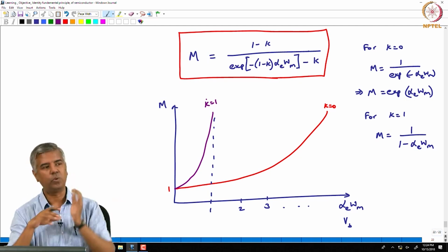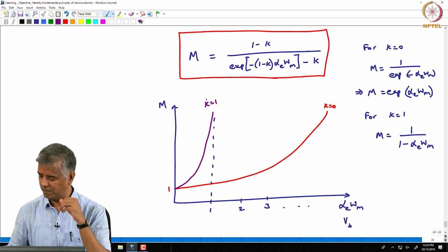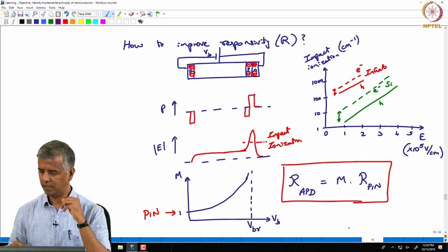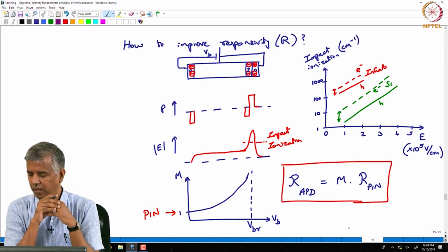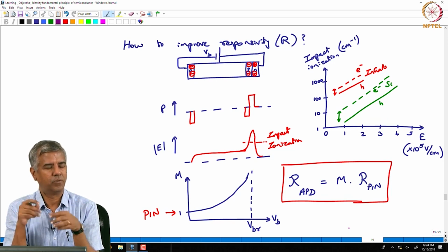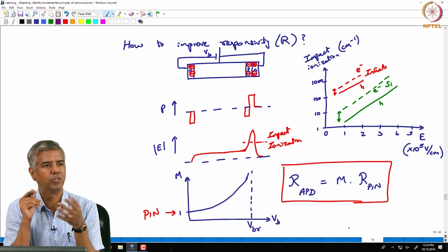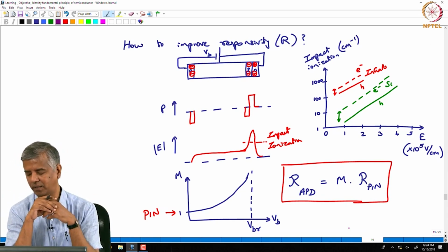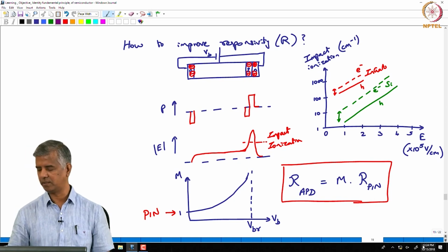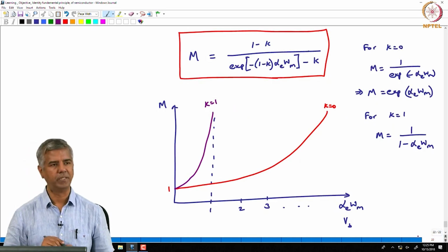Okay. So, you do not want k equal to 1 from that perspective, because if I go back and look at this discussion we had in this impact ionization, the dotted and the solid lines are overlapping each other. So, for the same electric field, both of them happen, right, both of them have the same threshold. So, both of them happen, and that creates more uncertainty overall in your secondary electron hole pair generation. So, that would be an issue here.